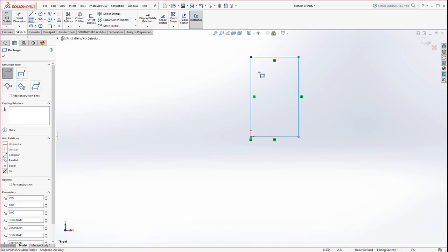Now, when you select that, you'll see that not only does a rectangle appear, but all these little green boxes. And those are another form of constraints. There's two forms of constraints inside SolidWorks. In the manual, you could read up on this if you like. But there's dimensional constraints, which we haven't put any in right now. And then there's an additional layer of constraints called relationships.